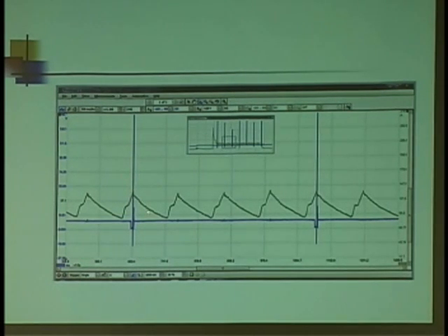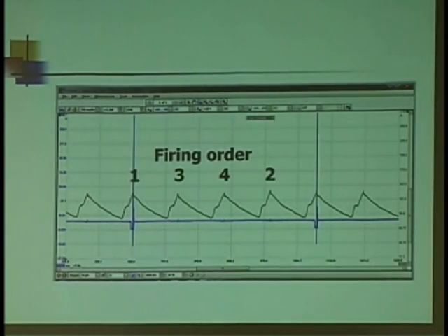So I got a pretty good feeling now. I know that this has got a 54 amp peak to peak. The trigger event, the ignition event, is occurring right at top dead center where it's supposed to be. So I don't think I have any issues with cam timing. I can use now that ignition event and use the firing order of the engine, so that if I do have a weak cylinder, I can identify which one it is.